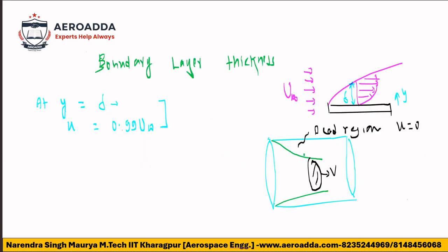See, if there is no formation of boundary layer, you will have the full diameter for the fluid flow. But now this is the diameter where the fluid is flowing. So obviously the mass flow rate will be less, because the mass flow rate is m equal to rho times area times velocity. So this area is reduced once the boundary layer forms. Always remember this.